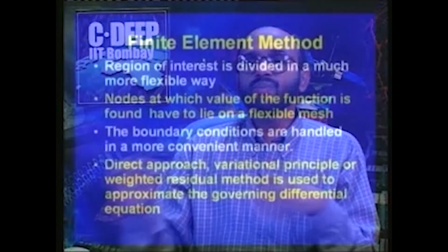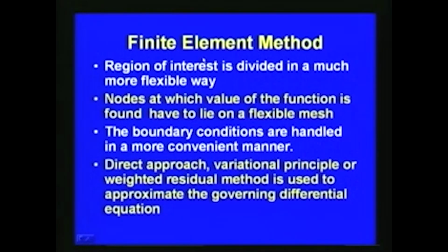Another important methodology used is called the finite element method. Here the region of interest is divided in a much more flexible way, and the nodes at which the value of the function is found have to lie on a flexible mesh. The boundary conditions are handled in a more convenient manner. There are a number of approaches in the finite element method. Some of the commonly used methodologies are the direct approach, the variational principle, or a weighted residual method to approximate the governing differential equation.